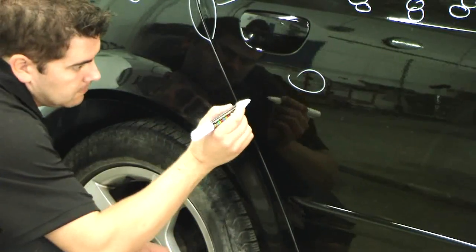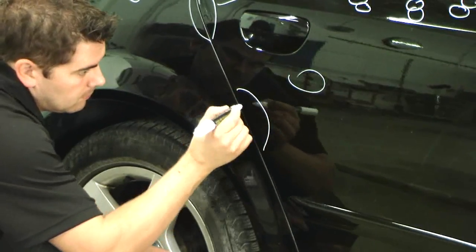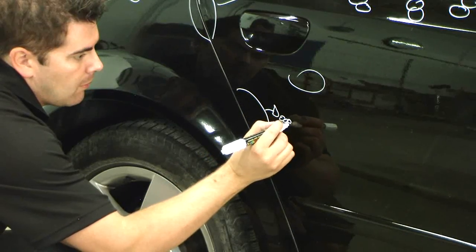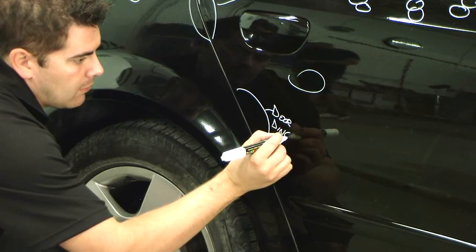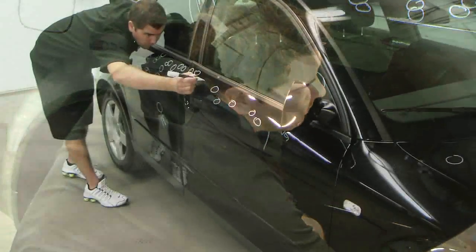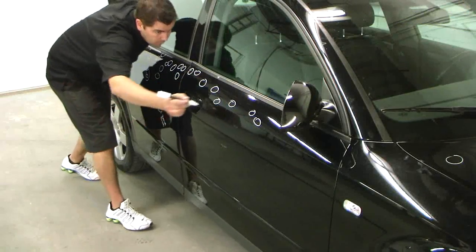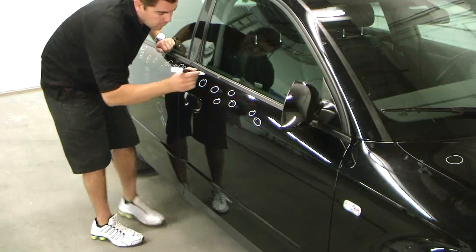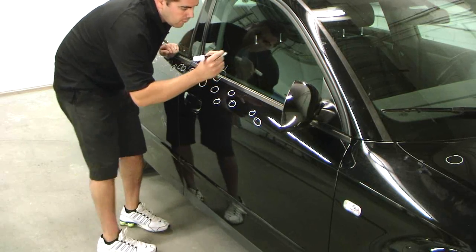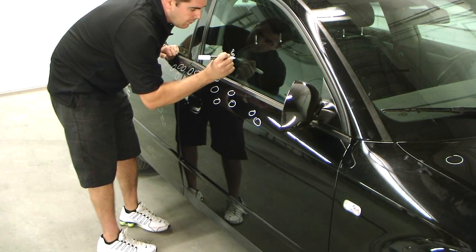As we can see here, there is damage to the side panel that is not a result of hail damage, but rather a door ding. Since we're already doing a repair on this panel, as a courtesy to the customer, this dent will be repaired at no charge. Moving across to the next panel, we can see that the belt molding has been damaged by a hailstone. We will circle this damage and make the adjuster aware of it.